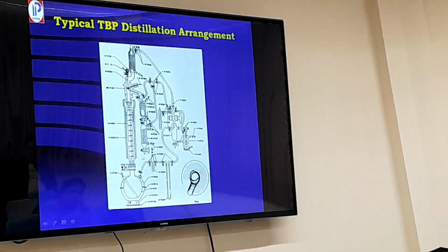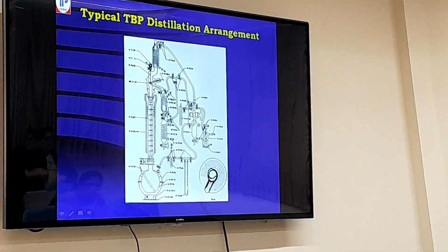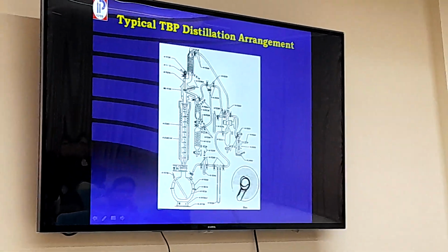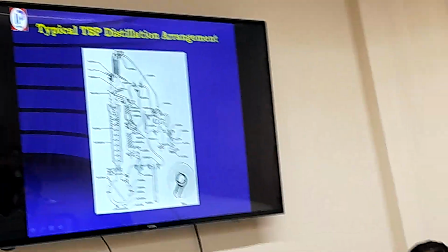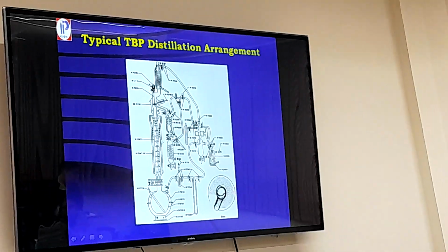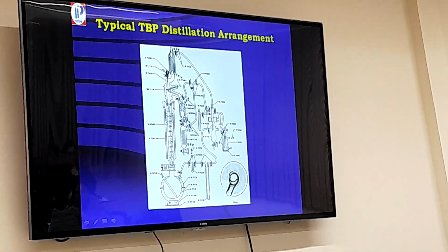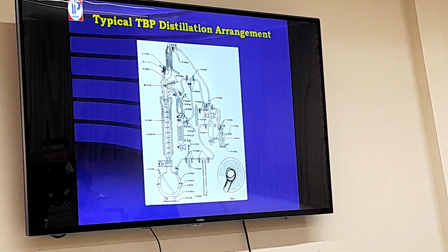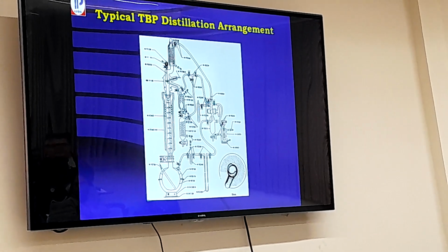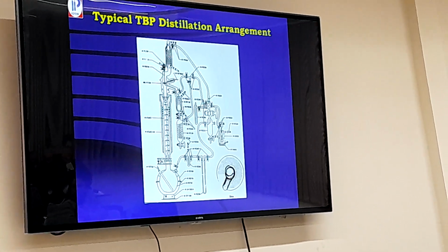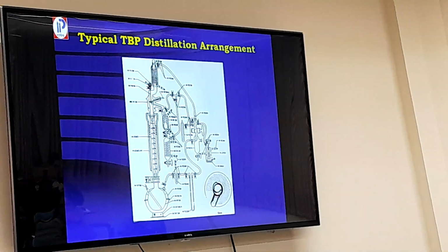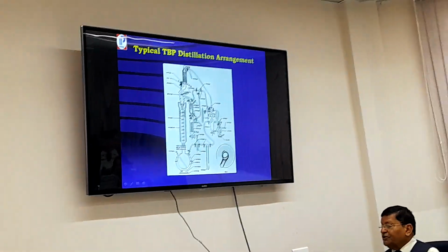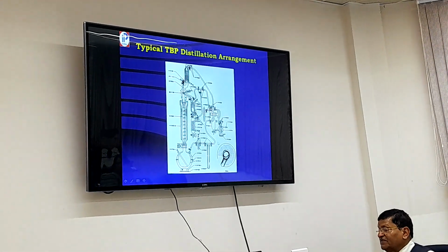Up to 205 degrees centigrade, we distill the crude at atmospheric pressure. After 205, we connect the whole system to the vacuum pump, and the whole system runs under vacuum. From 40 mm to 20 mm of Hg we apply the vacuum, and at this pressure we collect part of the kerosene, meaning 205 to 370, and the total diesel. This whole system is now under vacuum.